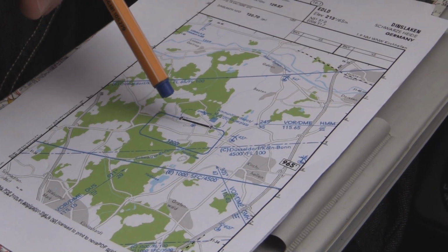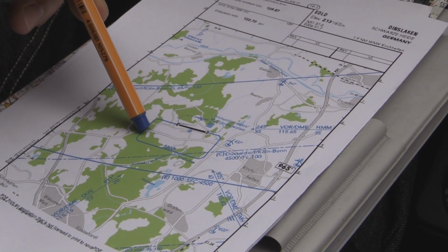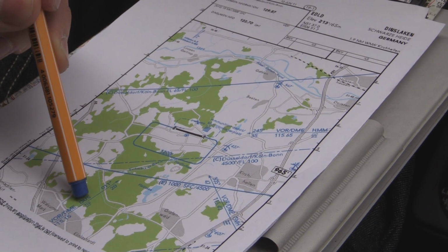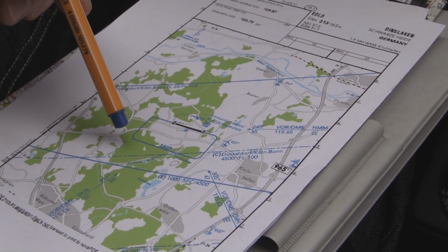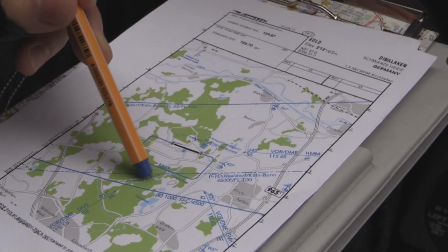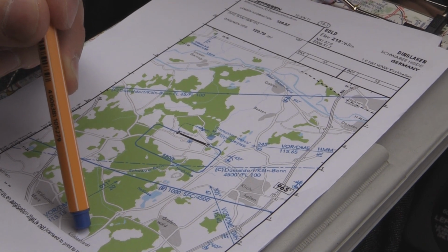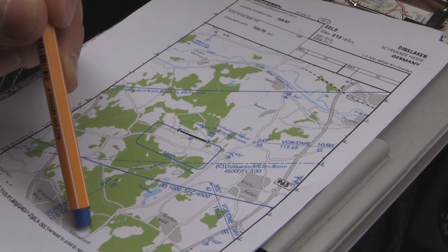And that depends on where we reach that altitude. If we reach it here, we are just going to directly leave to the south and of course announce it on the Unicom frequency, or otherwise we'll join the downwind and then leave via the downwind towards Essen. So, so much for the flight planning, and now let's go through the aircraft startup.